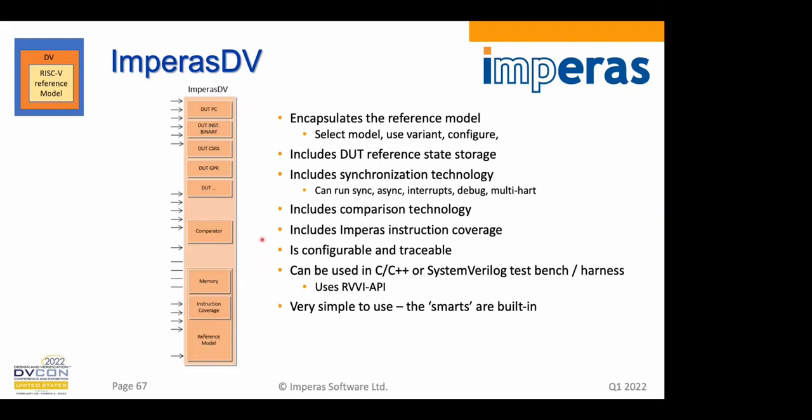It has synchronization technology in it so that it can do all the asynchronous natures of multi-hart, multiple cores in there, whether it's got interrupts and debug and other things that are going on. It includes comparison technology. It has built-in instruction coverage, and it's completely configurable and traceable. It can be used in a SystemVerilog environment or a C or C++ environment. So it's very simple to use technology with a lot of complexity under the hood, but it's very simple to adopt and use.